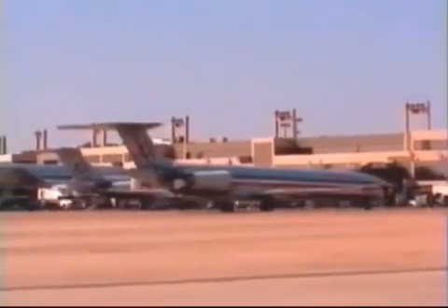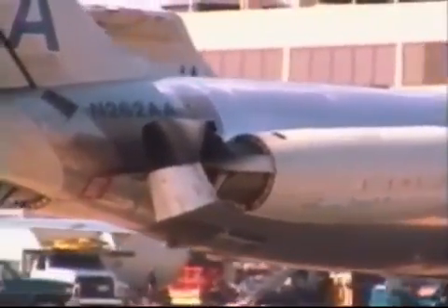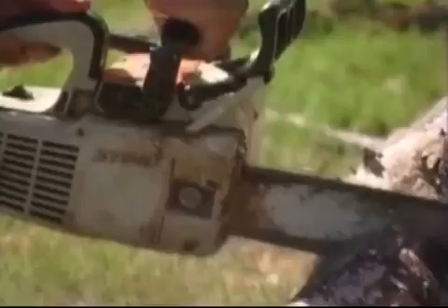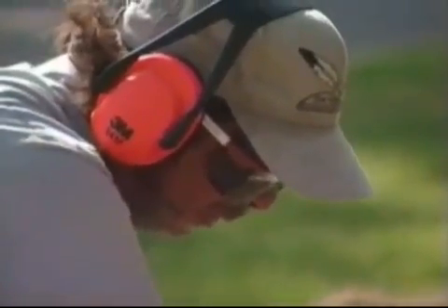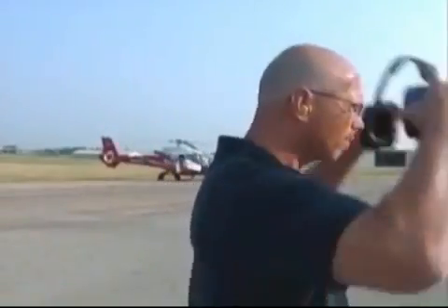Daily exposure to noise levels higher than 90 decibels can cause a hearing impairment. If ambient noise levels reach 90 decibels, it is necessary to use hearing protection equipment to prevent hearing loss. The best type of hearing protection is a combination of protection devices. It is important to emphasize the use of protective hearing devices does not interfere with speech communication during flight.